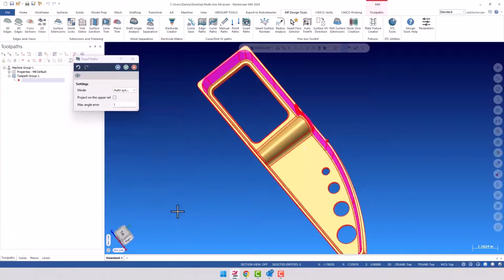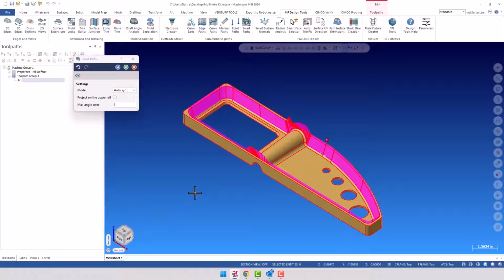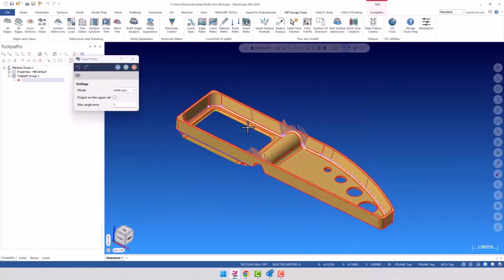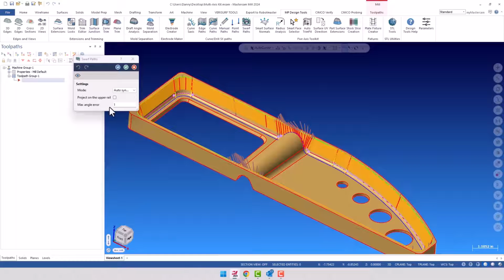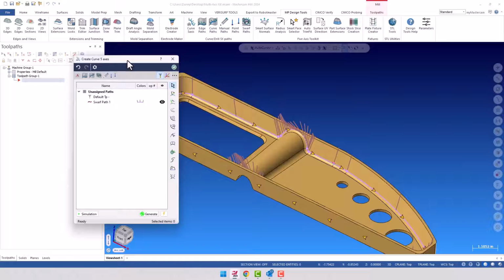I'm going to select this wall. The automation of this is, in the previous example I had already laid out all that wireframe, and I didn't want to sit there and draw that wireframe in front of y'all because it takes a few minutes, and then you have to go select all that wireframe. Here, it's already automated for you. It's very intuitive. You just pick this wall and say, I want to do a toolpath right here. I'll accept this, and now it shows me the toolpath and even shows me all the vector lines. Select OK to that.